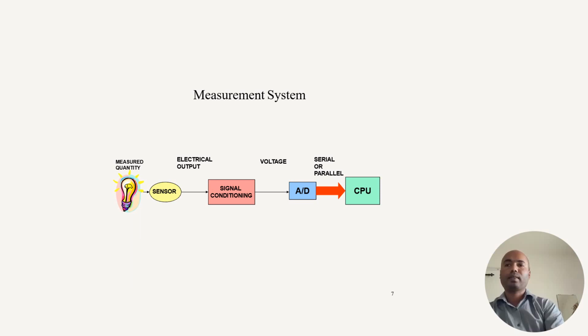For actuators and the ECU, we must thoroughly know what is to be measured while selecting the sensors. What is the measurable quantity or qualitative thing we need to measure? Whether we need to measure quantitative data or qualitative data. For example, quantity means the O2 sensor, which measures the quantity of oxygen present in the exhaust gases.